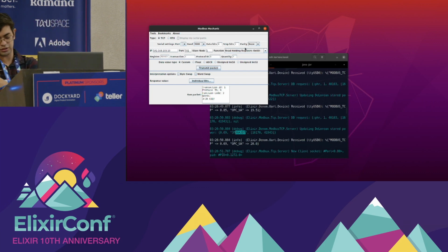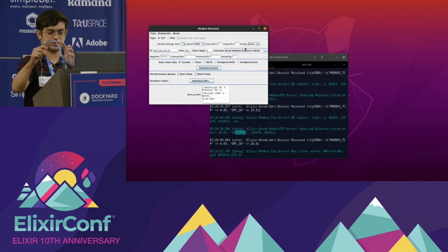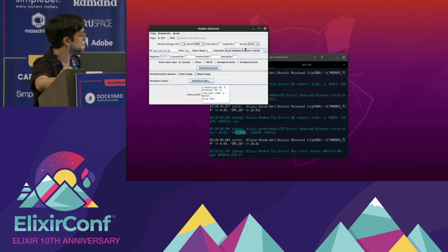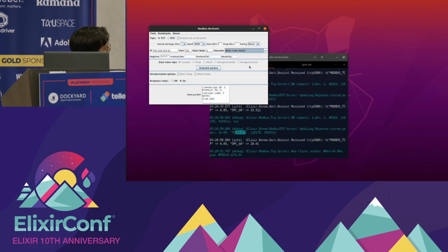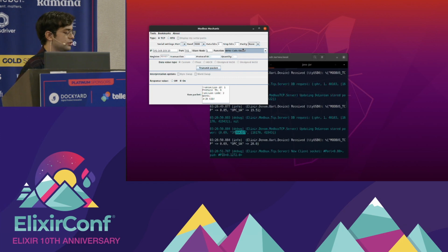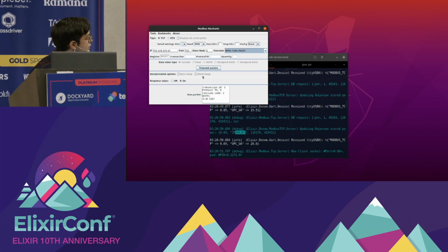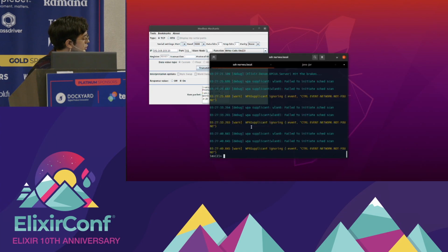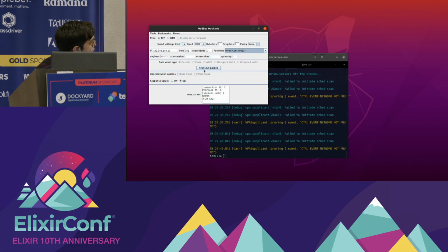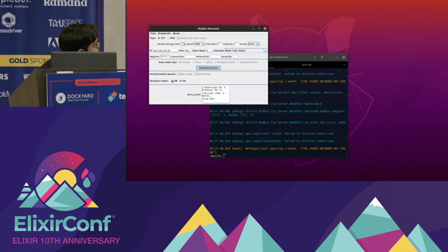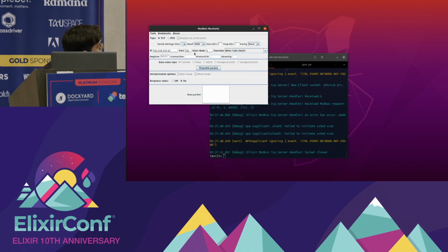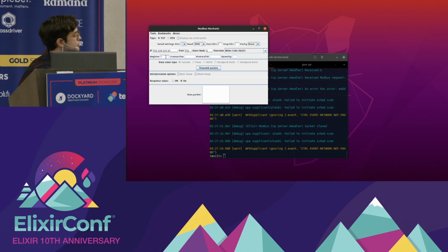I will disconnect the Arduino just to change the way that I'm going to use it. Now I will use the function of write a coil. I am exposing a variable which is a Boolean one, and here I can send if I want to turn on or turn off the variable. Here in the device, I show if I turn it on, it's on or off. Okay, I have to change the register. The register is number 1.